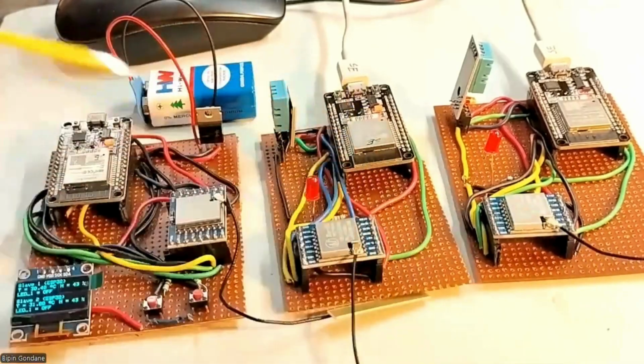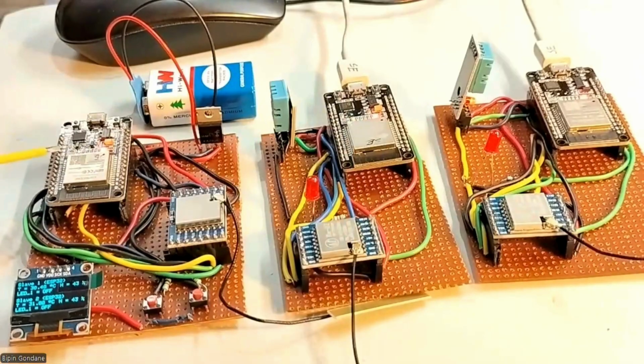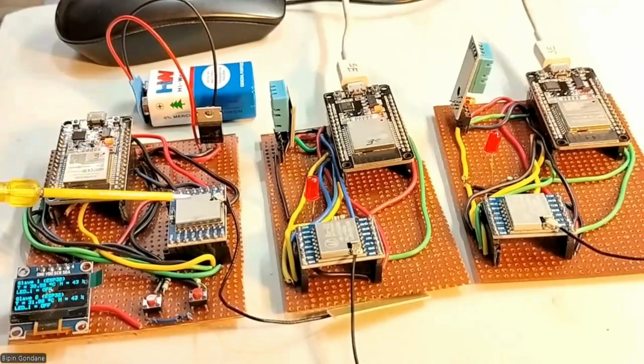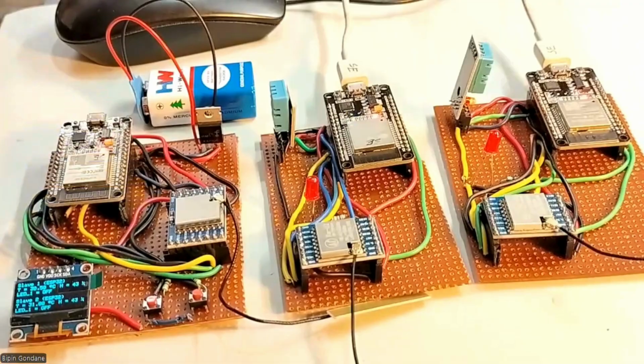So I will explain the master. What important parts does the master have? This is your ESP32 module, with Wi-Fi also. You can use it further. You can make a small LAN around the Wi-Fi and circulate the information. The second and most important part is this, your LoRa module. I have used the RA02, made by AI Thinker. For testing purposes, I'm using 410 to 525 megahertz, which is the ISM band.